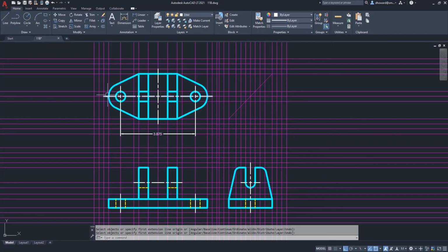typically measure from the outside of an arc to the outside of an arc when we're specifying the overall length. It is okay to do that if you put it in parentheses, but it's more important to show it from center to center because that's really how things are made. So if you were going to give the overall length of this thing, which I will do, it would be something like this. You would go from end to end,